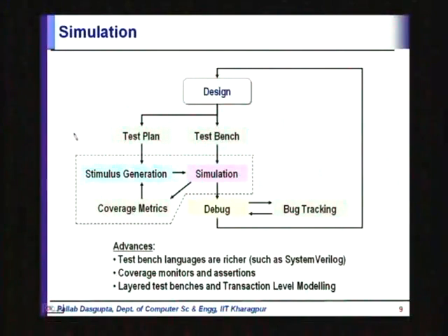Its job is to take the tests, which are typically written in Verilog, and integrate them with the design, so that when the two are simulated together, the tests are fed into the design, and similarly the outputs from the design may be recorded or dumped. Now, alongside this test bench we have a very important thing which is called the test plan.